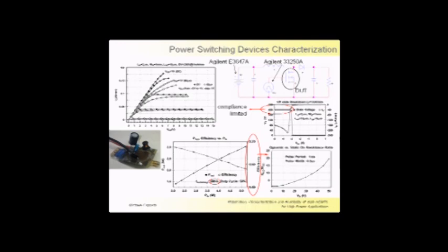Measuring the output power and efficiency on wafer in this power switching measurement setup, we got at 2 megahertz efficiencies in the range of 55 to 65%, possibly due to the dynamic versus static on-resistance increase while increasing the drain bias.